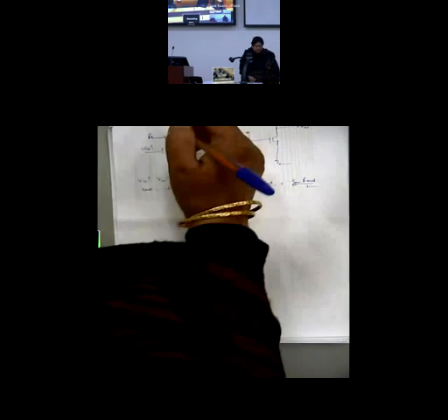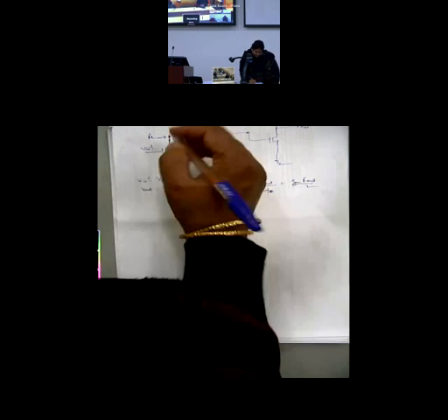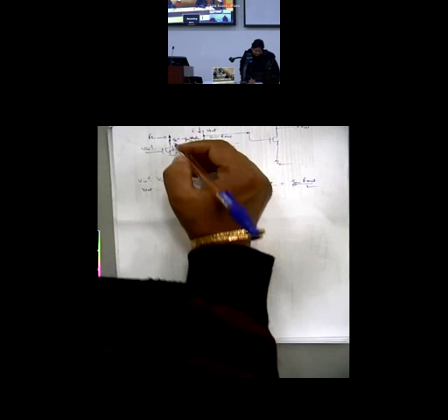So what is to be done? A reflection mechanism: reflecting one input, or replicating, mirroring one current into the next term. That's what I have to do. I can have this current I, and if I can bring this current I reflected here, then the net current through this will be 2I.